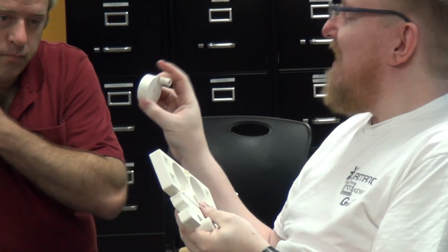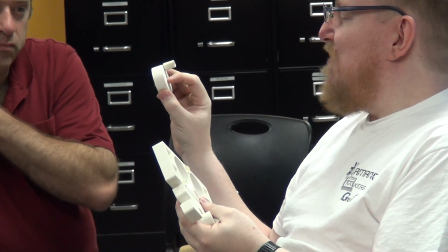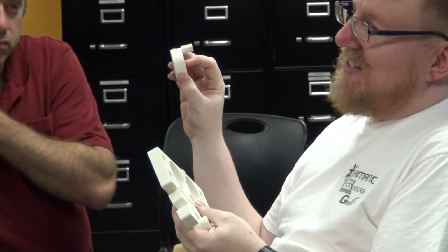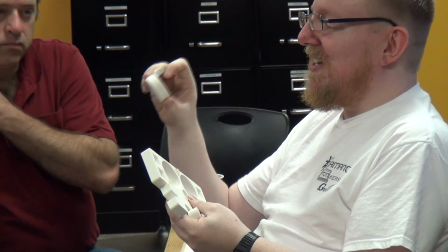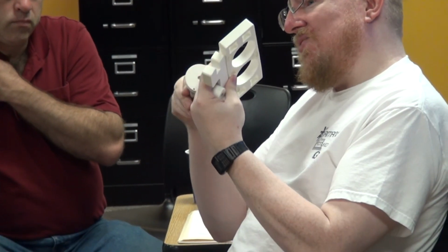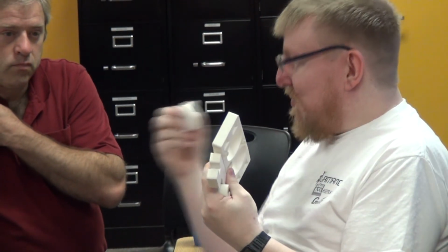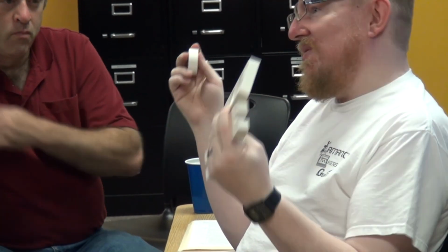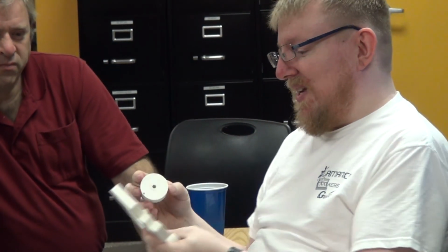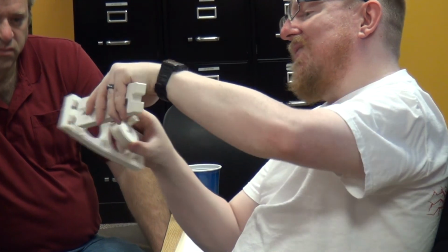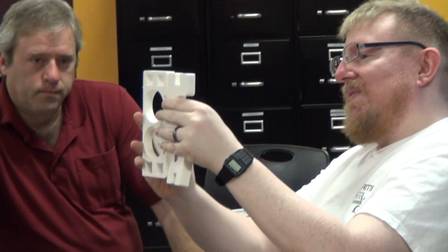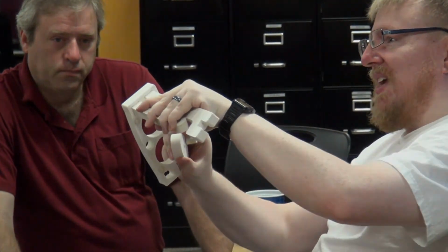And this has a hexagonal hole. I machined that roughly as a hexagon, but it's going to have rounded edges, and then the drive shaft, the thing that this drives when it's put together, if you just pressure fit that, this stuff's soft enough, it just moves out of the way, and you get a nice fit. These go together, and you can see the dog bone fillets on this so that it will physically go together.